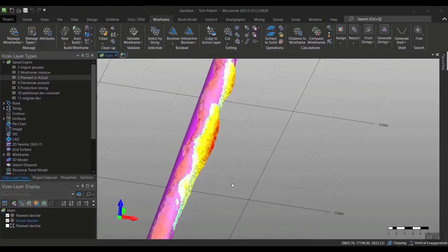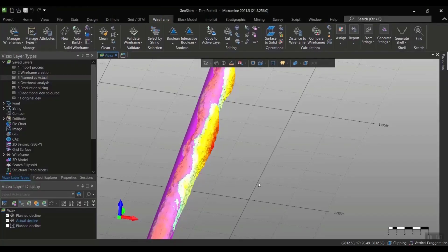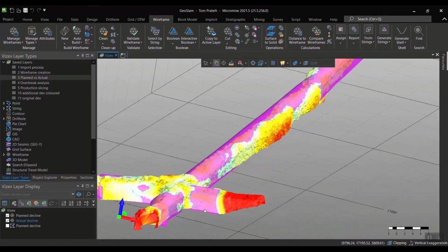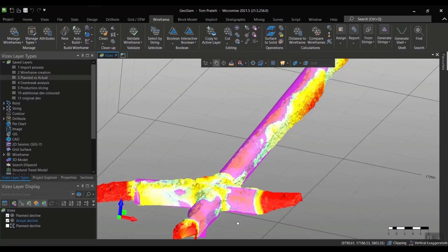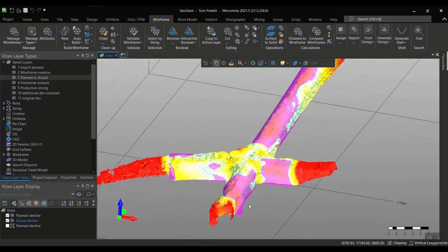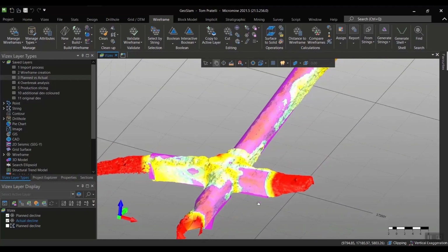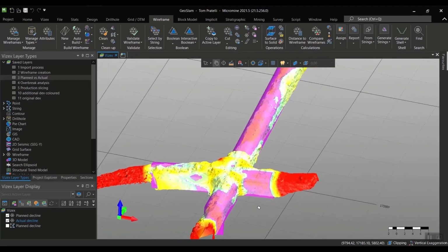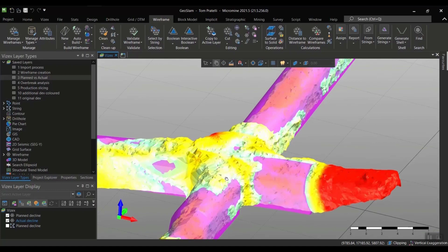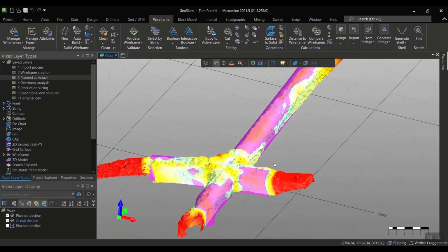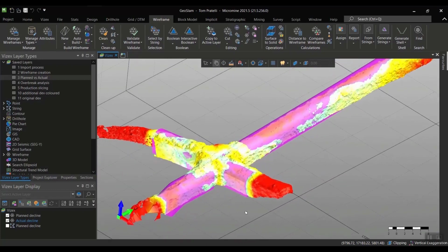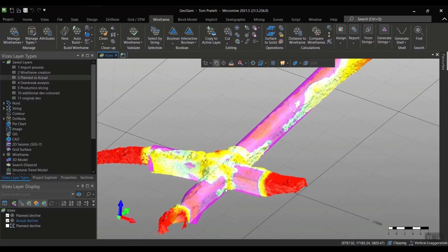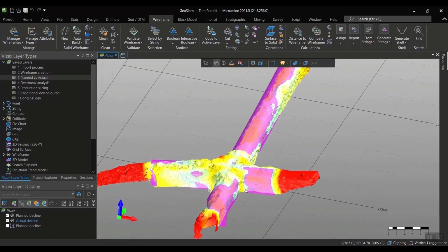So there's a lot of great applications here for looking at overbreak and underbreak. In this scenario, we've been particularly interested in looking at overbreak analysis, but the application of comparing these as-built wireframes versus our actual plan is also applicable to something like convergence, where we might want to monitor slope or any movement within tunnels, and this would provide us details as to if there's been any particular movement with any structures or anything like that.